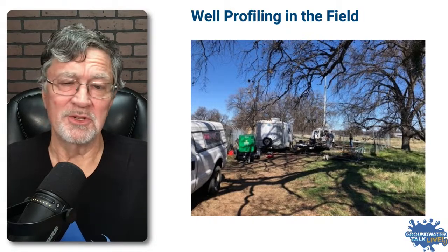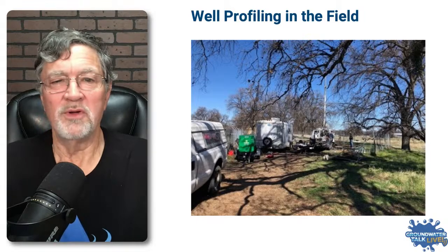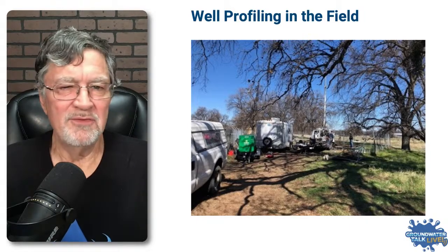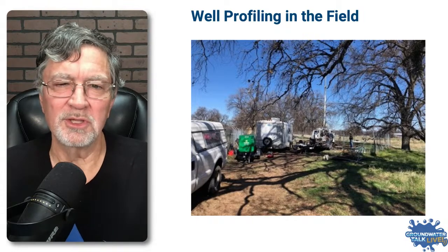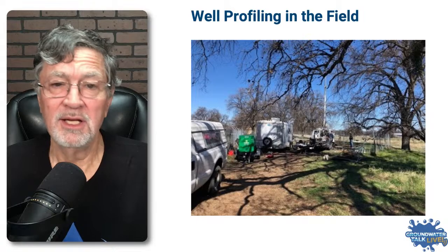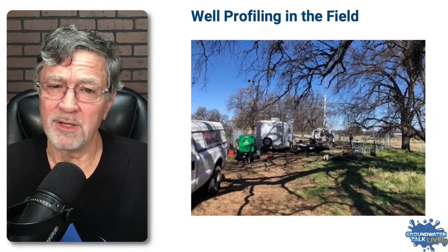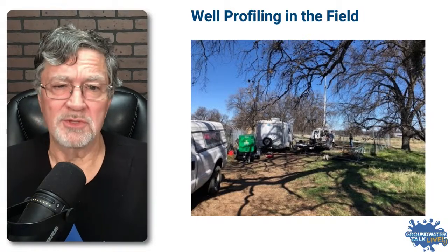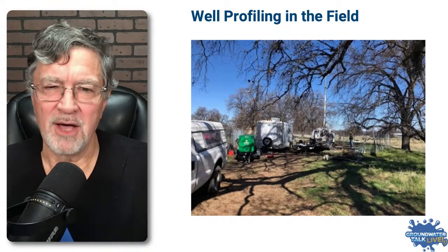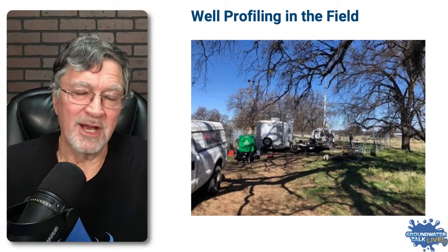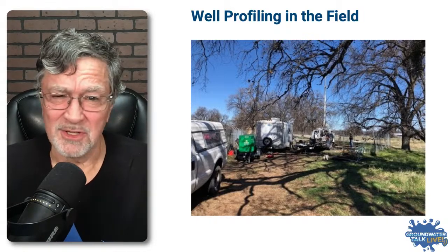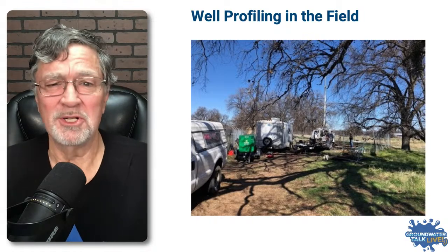And instead of doing zone testing, we've actually started doing the well profiling. It gives you a much more granular look at the well, where the water's coming in and where the contaminants might be coming in, and allows you to design the well right up front. Really no additional costs in doing that, other than the profiling, which is actually taking the place of traditional zone testing, hideously expensive, and you don't get much detail.